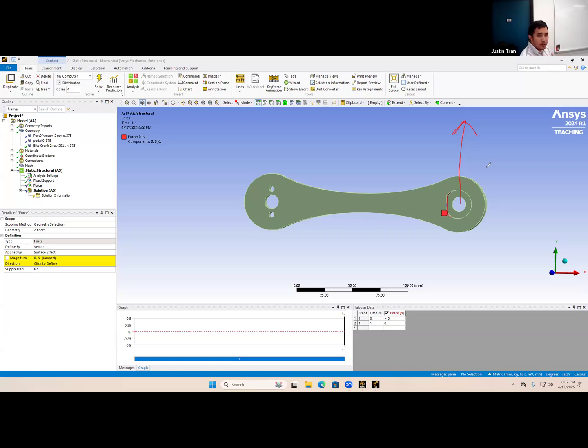So it's a little bit of a shift in paradigm in terms of how we do our simulation. Usually what I tell people when you're running a static simulation is to think of the worst case scenario for your simulation, and that should be your load. For fatigue life, you're not looking at a worst case scenario, you're looking at a very typical scenario, something that this part is going to experience hundreds of thousands of times, millions.